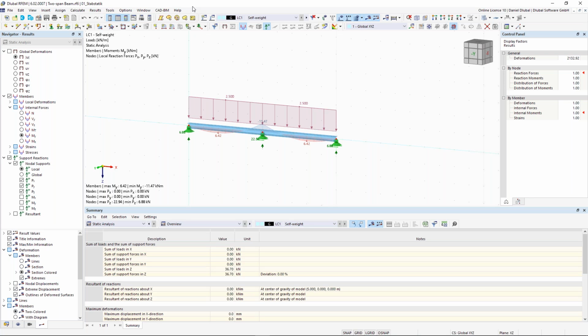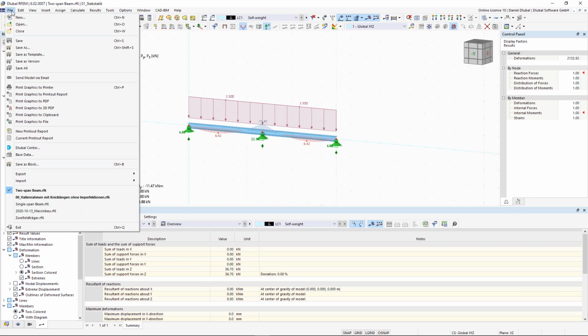It depends on the projects you want to calculate and analyze. What we can offer too is that you can create templates. You can save here, for example, this continuous beam as a template with those predefined load combinations. When you refer to this template, the defined load combinations will also appear. Just go here to File, Save as Template, and when you open this template, it opens the project with these definitions you made. That's a good point.